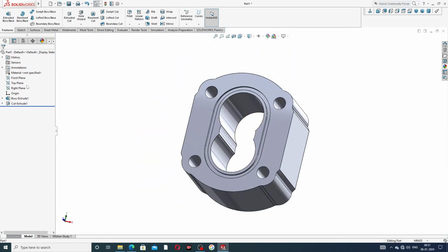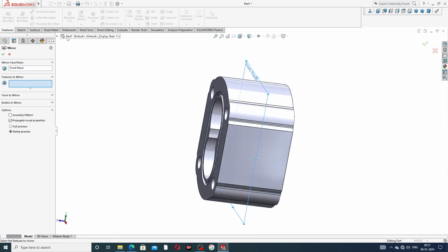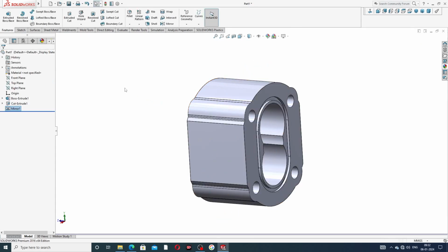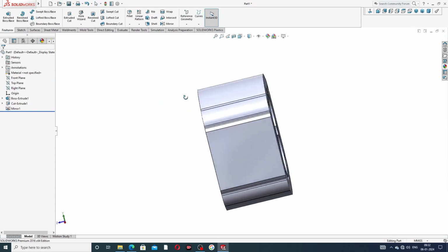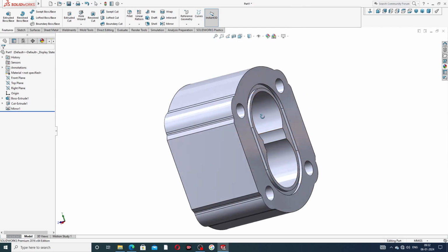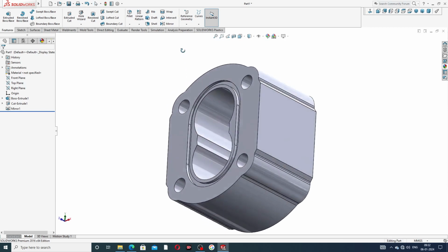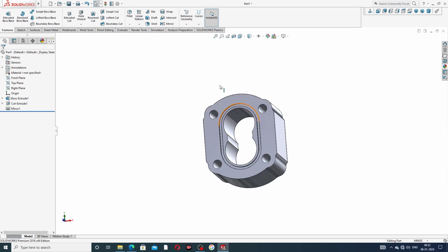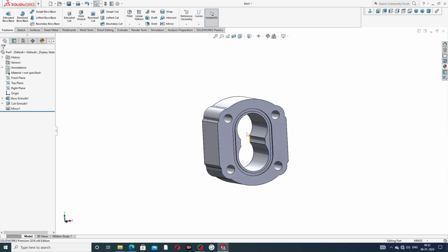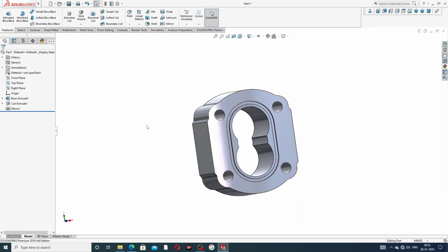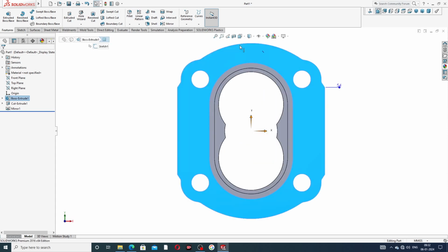Okay, and also use a front plane because this uses a mirror, and select this and cutout is this, and click OK. This back side is also drawn correctly here, and both sides use a rubber washer, and this is perfect.